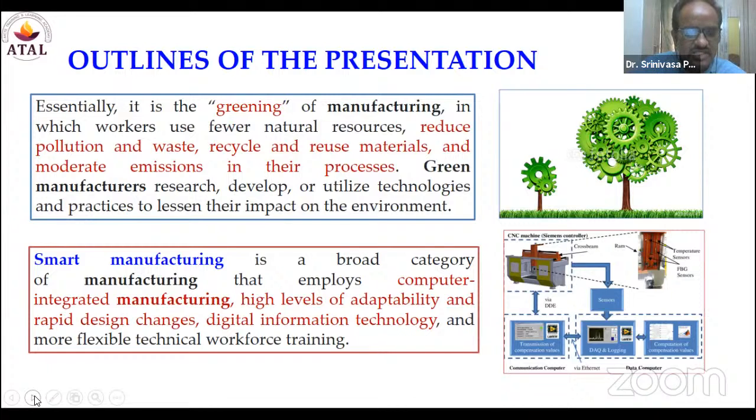It means the CNC machine is ready to work based on the 3D model or 2D model. It is going to detect features from the drawing, and CNC machines nowadays are capable of extracting the features from the part drawing and generating the part programming codes based on the part geometry features. CNC machines are able to understand the program and repeat the task.